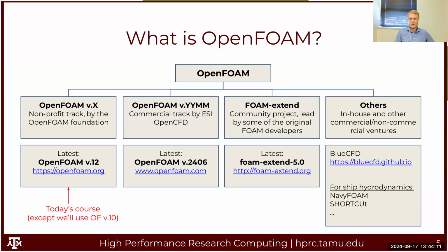So if you're not quite sure you want to take the plunge and get a brand new operating system to run OpenFOAM under, you can try it out on a more familiar environment, if Windows is your most familiar environment. I should say that the version of OpenFOAM running in BlueCFD is considerably slower, using the same hardware, than if you were running it natively on Linux.